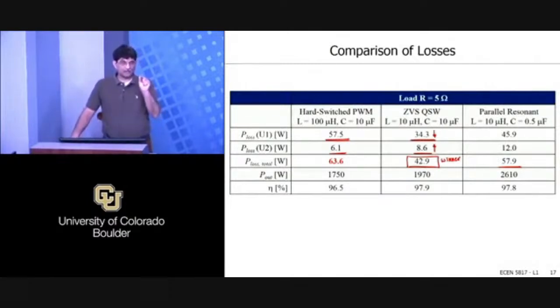are now happening at higher current, again because of the higher ripple, right? So the device has to turn off a larger amount of current, and as we will see, how much current you turn off also determines how much switching loss you will have, right? I mean, we know it's reduced, but it doesn't go to zero, and the amount depends on that current that you have to turn off. So that's the other thing that's going on.